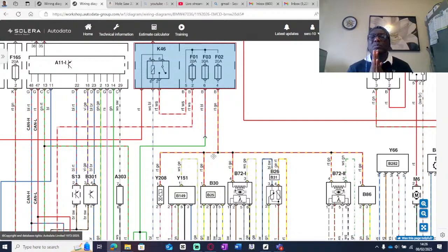A signal wire cannot be shared for the simple reason it is carrying information that is coming from the sensor. That is particular information. If it's a speed sensor, it's a speed sensor. How can you share that with a crankshaft or with a temperature sensor? It can't be shared. Only the powers can be shared and the grounds, but not the signal itself, because we want to know what the signal is saying for a particular sensor, not bringing 10 sensors together and then having one wire. How are you going to interpret that? I hope you see what I'm trying to say. Sometimes my English limits me.